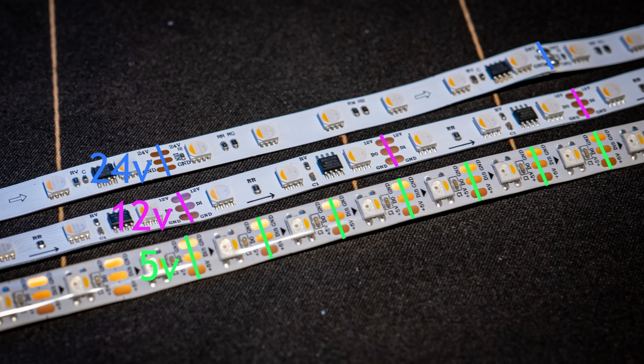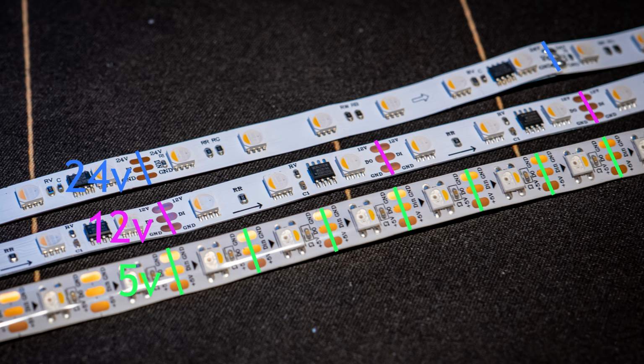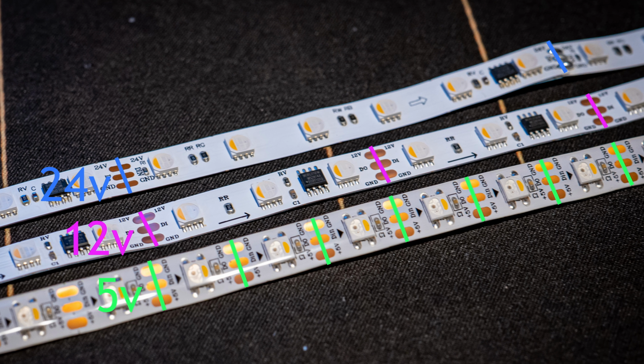That way you can drop down the voltage in series over those 3 LEDs and you get down to a voltage that the LED can use. The downside, however, is that those 3 LEDs always need to do the exact same thing to always have that voltage drop. If one of them would be doing something else at that moment, well, the voltage drop wouldn't apply and you'd blow up the LED basically.